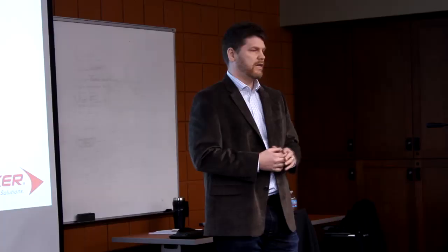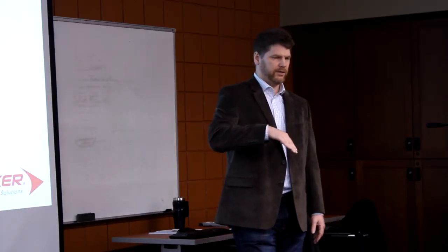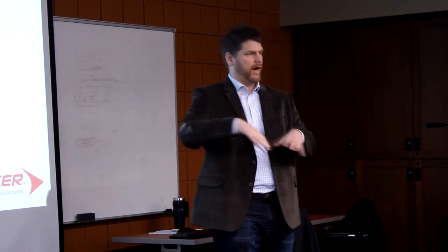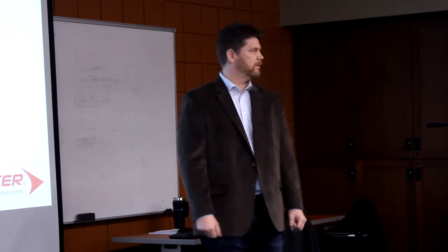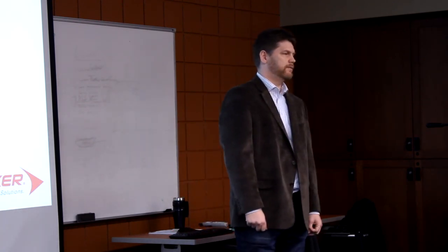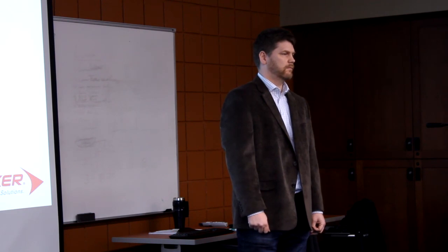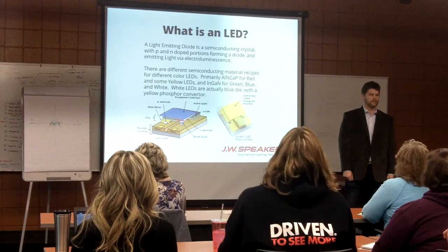The other thing with OLEDs is they don't hold a lot of current density, not like these. These can hold a ton of current density, and therefore the luminance of OLEDs is way lower, orders of magnitude lower, like 100 times less almost than this. So when you use an OLED, typically you're not using a lot of optics with it because it's a very big, wide source, so you can't really direct it as well. And there's the color consistency due to temperature. Over time it shifts the colors, so for signalization, that's a problem.